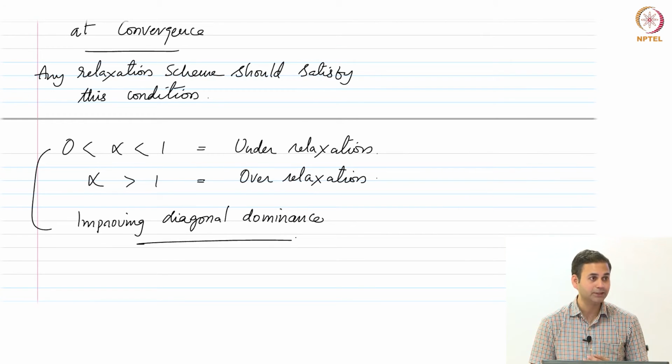So, essentially that is the reason why I said if you have strongly nonlinear problems, then you have to look at under relaxation, because the changes in the solution could be much quicker, which might make it difficult for the system to converge, okay. So, that is the thing.